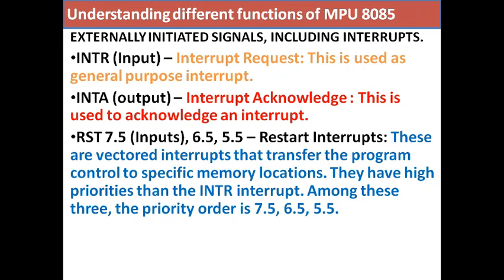So in order to save the microprocessor's precious time, an interrupt driven data transfer scheme was introduced, where if data is available at any port of the input output devices, it will first request the microprocessor by sending a signal through INTR.